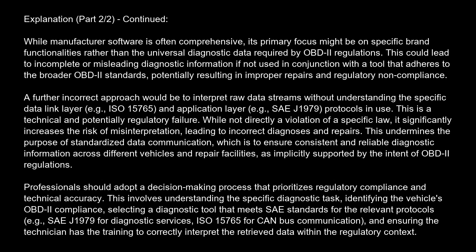Professionals should adopt a decision-making process that prioritizes regulatory compliance and technical accuracy. This involves understanding the specific diagnostic task, identifying the vehicle's OBD-II compliance, selecting a diagnostic tool that meets SAE standards for the relevant protocols, e.g., SAE J1979 for diagnostic services, ISO 15765 for CAN bus communication, and ensuring the technician has the training to correctly interpret the retrieved data within the regulatory context.